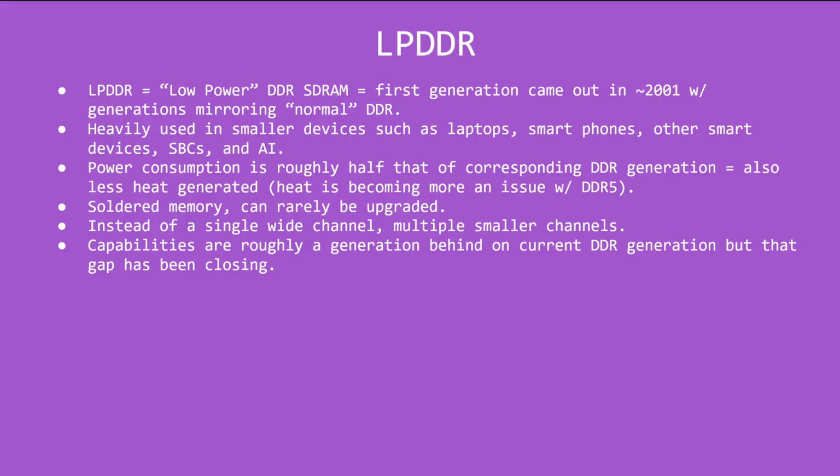Its capabilities are roughly a generation behind its corresponding DDR generation. So LPDDR5X, sort of comparable to DDR4, give or take. Mind you, that gap has been steadily closing. So LPDDR is starting to really compete with lower end regular DDR.